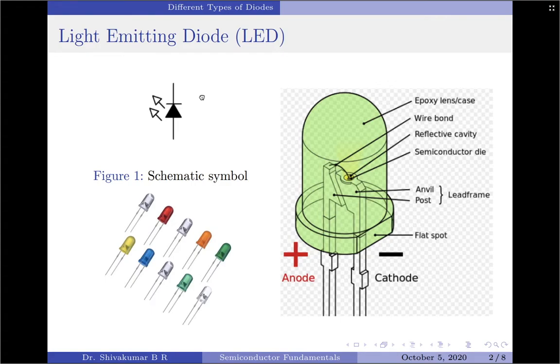When reverse biased, the LED behaves like a switching diode, that is, it looks like an open switch. Unlike switching and rectifying diodes, LEDs' maximum reverse potentials tend to be relatively low, perhaps just a few volts.